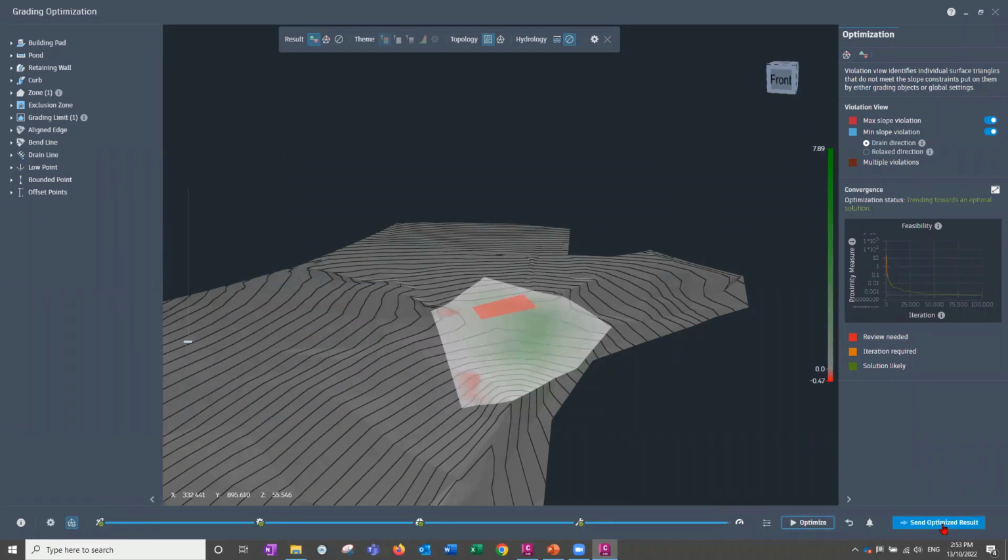So the thing that it's done, we had all this before. You may not have seen it, but we have had it. It's changed my surface here, and I can export this back to Civil 3D to have a new optimized surface. It'll also take back things like the feature lines, the break lines of these changes. There were issues with the feature lines crossing in some places.